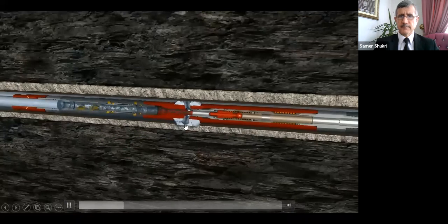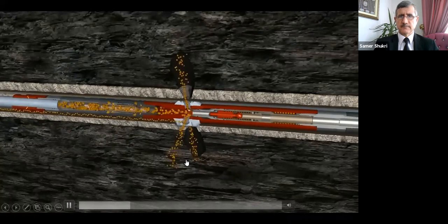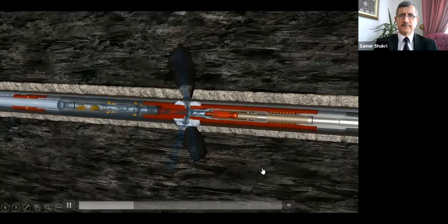Once at a jetting pressure, a sand slurry is introduced to begin jetting through the casing, cement, and extending a cavity into the reservoir. You see, this is perforation. This process can be repeated multiple times until the required quantity of perforations are made using sand particles. Flow is switched to clean fluid to flush the perforator.